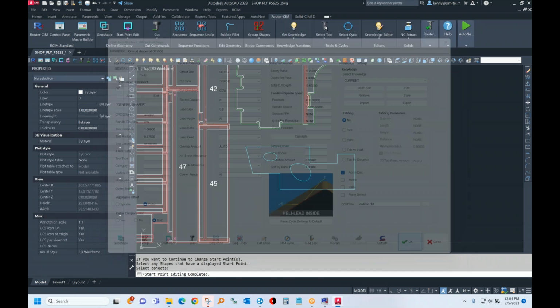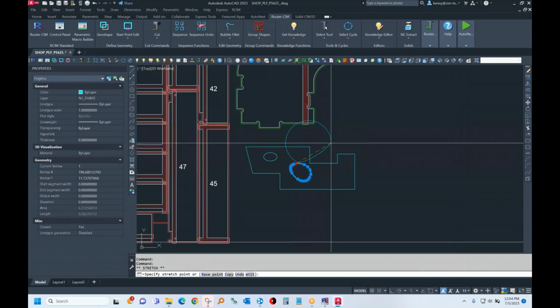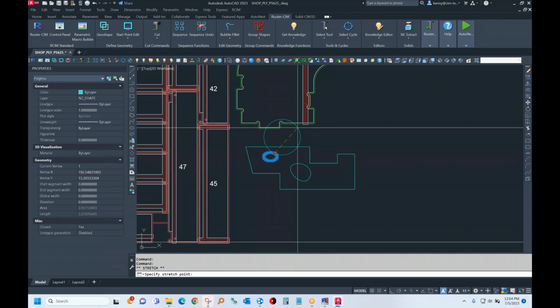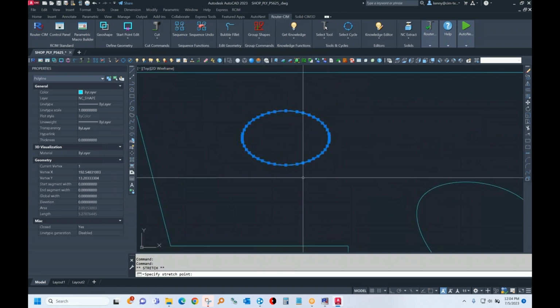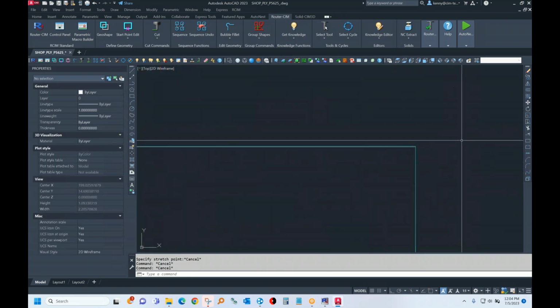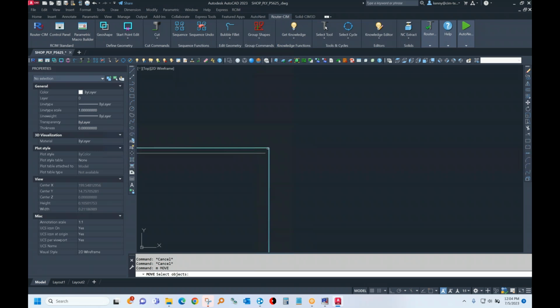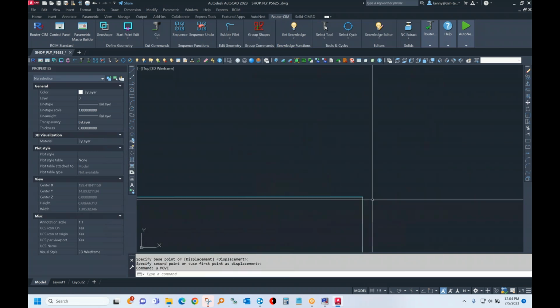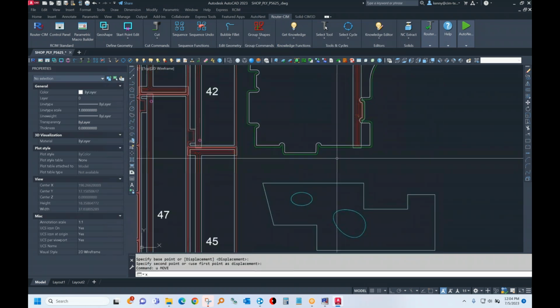Okay. And at this point now, this spline is arcs, much less than a bunch of little lines. And so is the ellipse, a bunch of little arc segments. They're all nice and tangent. And in this corner, it fixed the geometry within a tolerance. It made me a new shape right over top of the old one. Great, it fixed that for me, okay?